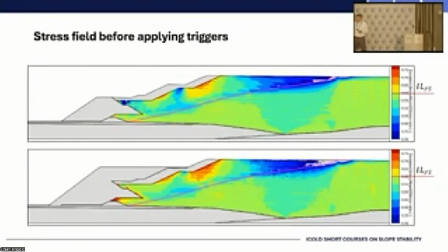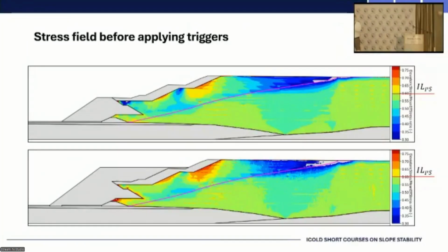Not just on the potential failure surface, but throughout the model. Why? Because the instability line is an outcome of the choice of the peak and undrained strength. So if you pick 0.21 sigma prime V0 or 0.04 sigma prime V0, the instability line is an outcome. You cannot also pick that. And it happens to be very close to the K naught line as we calibrated it.